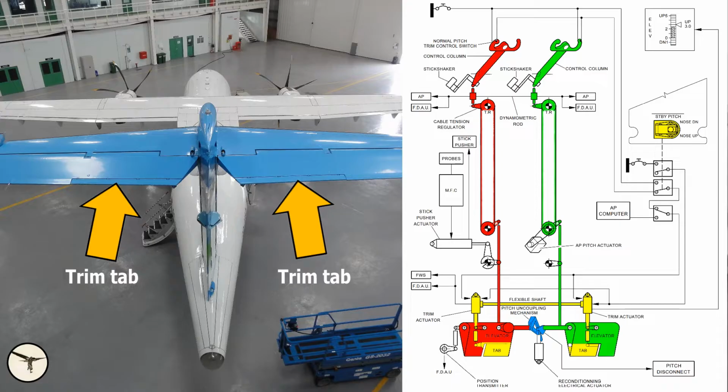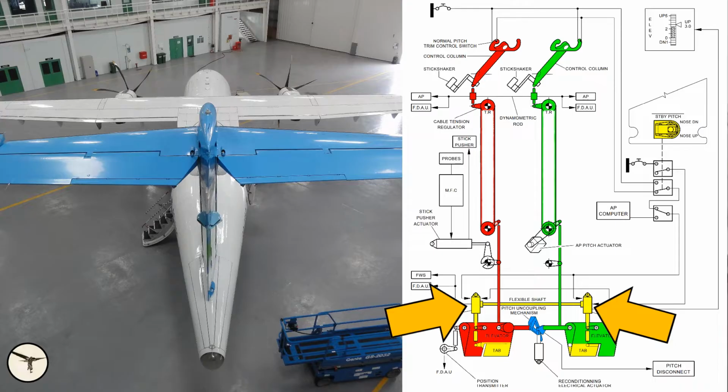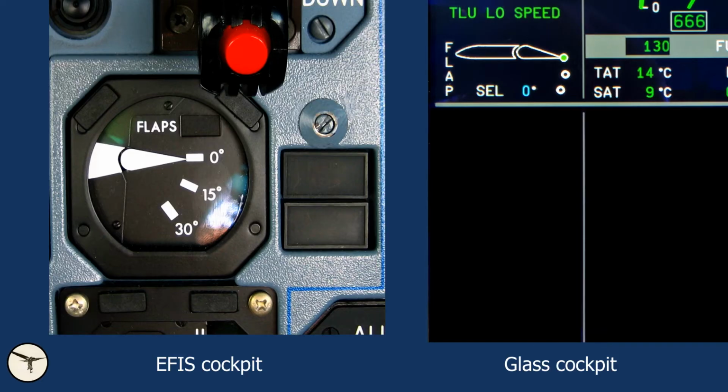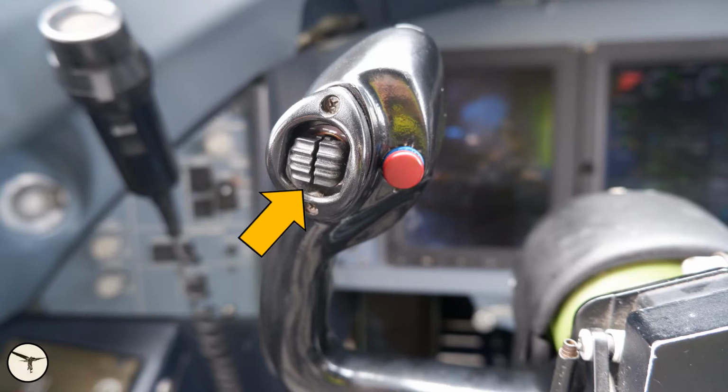Each elevator has a trim tab operated with electric actuators. The actuators are synchronized with a flexible shaft. If this synchronization fails, a pitch trim asymmetric alert is triggered. Pitch trim is operated with two rocker switches on the control column, and both of them must be pressed in the same direction to operate the trim. Full trim travel takes 30 seconds. An aural warning sounds when the pitch trim runs for more than 1 second.